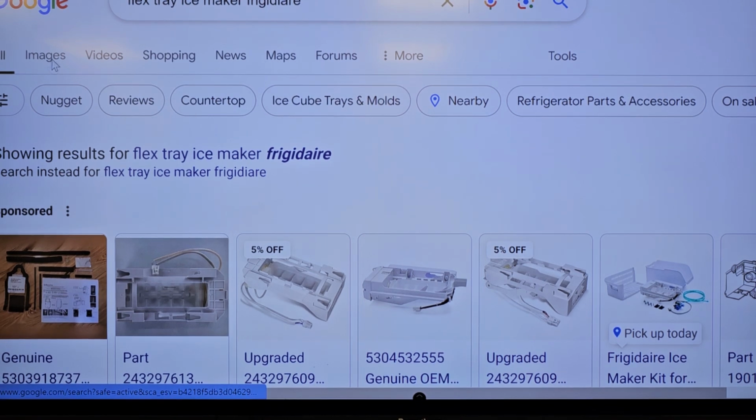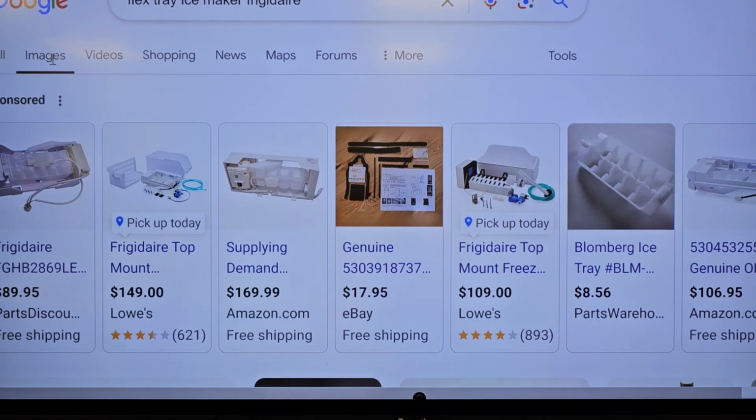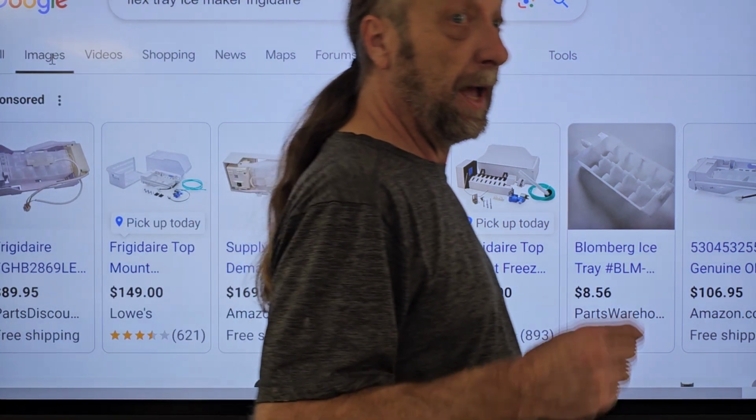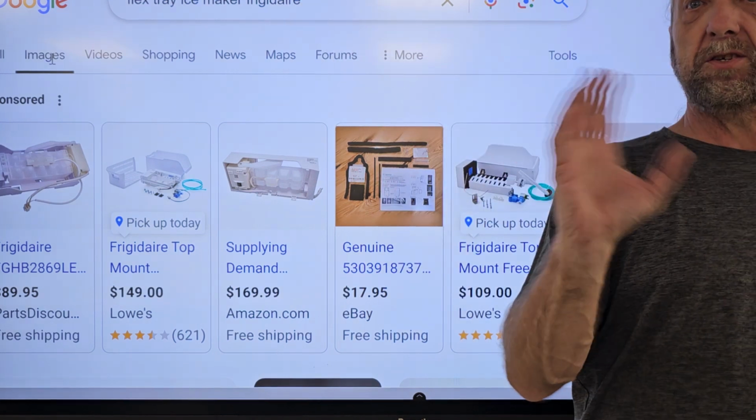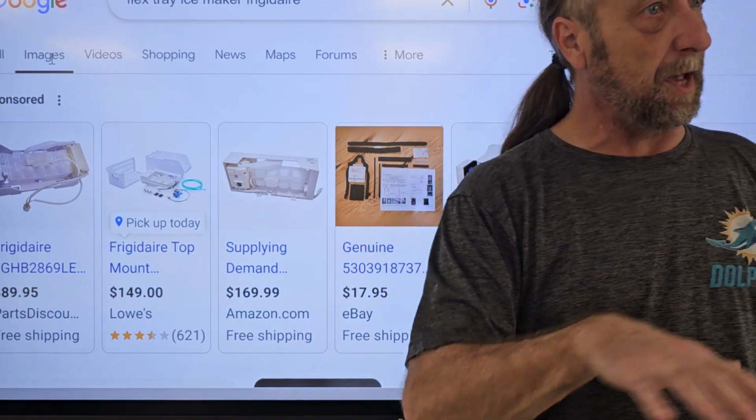Couldn't we just go pull it up? Huh? Couldn't we just pull it up? It's right here. Okay. On the bottom of this tray right there is the tray sensor. That is what is telling the ice maker, hey, it's ready to drop. That's all it is, a thermistor. All it is doing is sensing temperature.